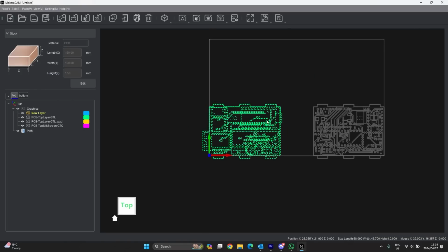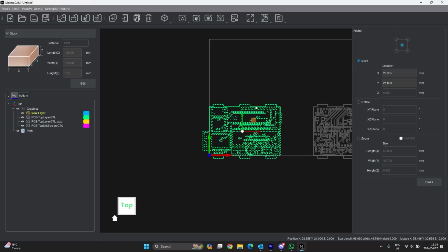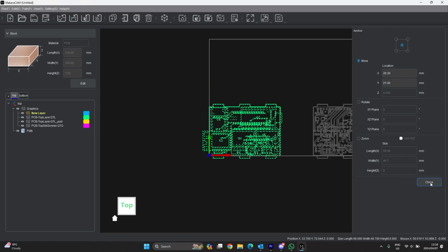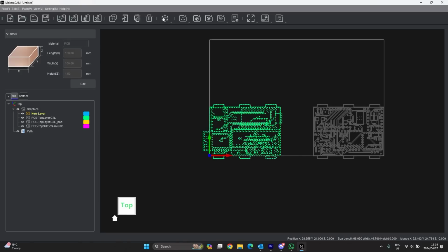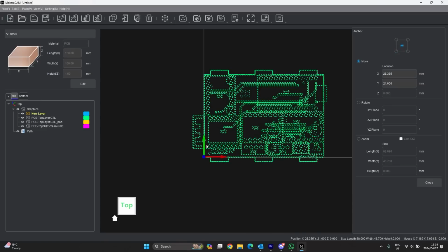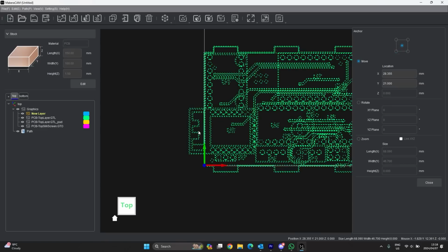But you can also do multiples, so copy. And if you select everything over here, you can hit M and then move everything around. That's just a shortcut for moving it. Basically, if you select everything, you go here, you can transform, so you can move this part relative to what point you select. But I want to move this part just a little bit inwards, just so it actually clears the stock. And that's a silk screen part that's overlapping there.